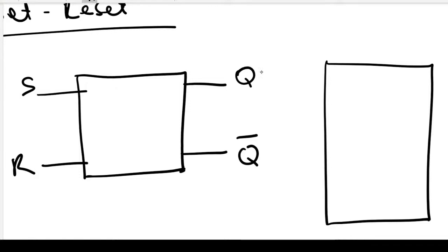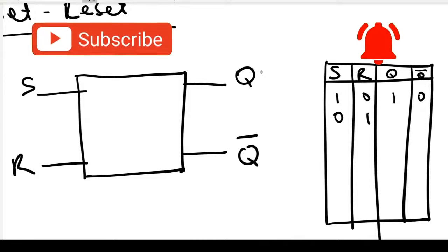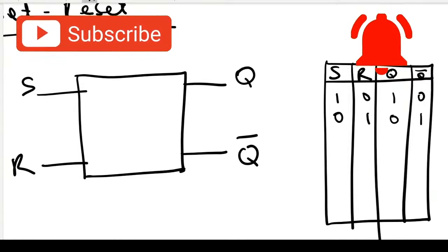These are all positive going: set, reset, Q, not Q, or Q bar. I need to rewrite this so that my not Q will have its bar. So if I have 1 and 0 here, and when I do 0, 1 here, then this will reset to 0 and 1, and so on and so forth.